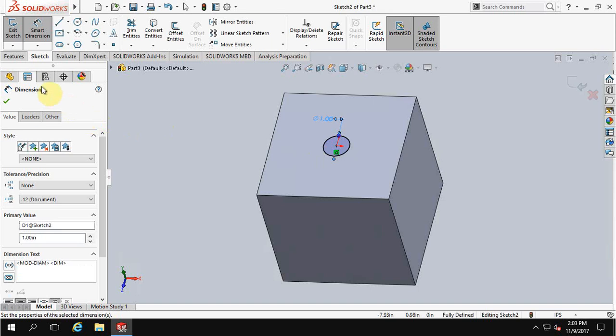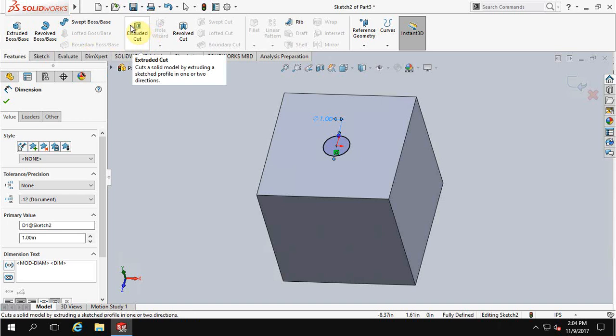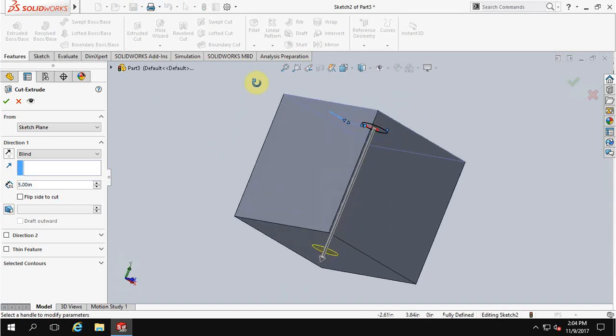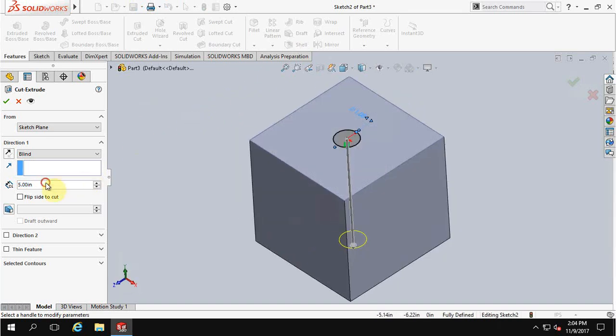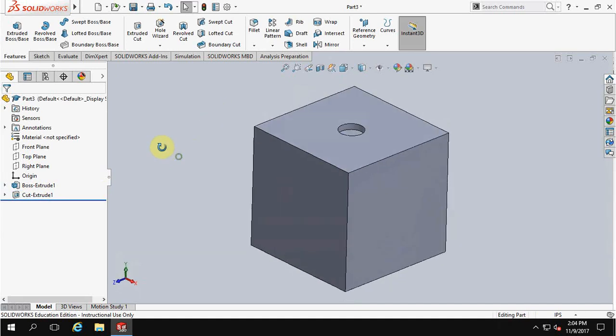And then this is where things get a little bit different than Onshape. We can't actually emboss or just do a regular extrude on this one because we actually want to remove material. So we have to consciously tell it to do the extrude cut feature. It's not the same thing that we can just reverse. So now it's going to say, all right, here's your circle. It's automatically picked it for us, and it's going to actually try and cut all the way through it. We don't want to do that. We just want it to go down 0.25, hit enter, and then enter to apply it. And now we have our hole going into the top.